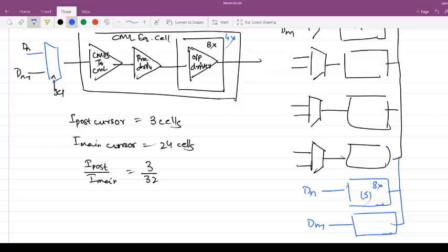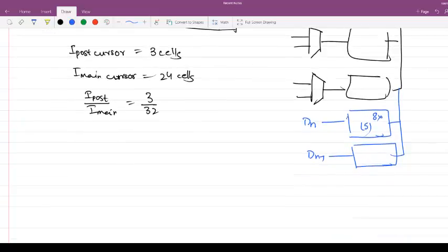The other thing is, as you keep on segmenting all these things, it is going to add parasitic capacitance at the output. No doubt about it. And if you are hitting a high speed, then the parasitic capacitance causes more problems. That is mostly handled by using bandwidth extension at the output driver. The simplest bandwidth extension is to use an inductor at the output driver, basically when your parasitic capacitance is becoming too high.